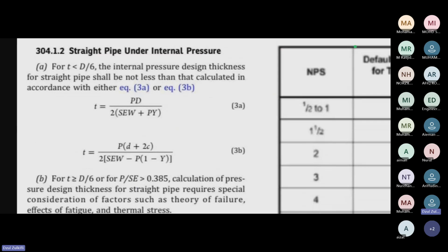But if the ring is really big, then it is an obstacle, because when the ring is too big, essentially a big component usually has a big weld attached to it too, if it's thick and all. So that causes an area where you can have higher stress. Number one, residual stress from the weld. Number two, when you have two thick big components adjacent to each other welded, there is a lot of stress when they are trying to move, even in a small displacement.